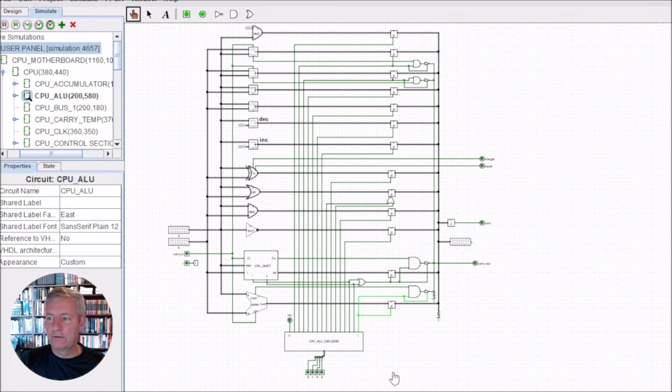So the ALU previously, we had only 3 inputs, and we had a 3x8 decoder, and we could choose 8 different functions. So I've extended this, and I've put an extra line going into the ALU. This gives us 4 lines coming in. We then have a 4x16 decoder. It gives us 16 functions that we can do in the ALU. So it extends the ALU. Again, we'll go through the ALU extension and the changes in another video. It's just an overview that we're doing here.